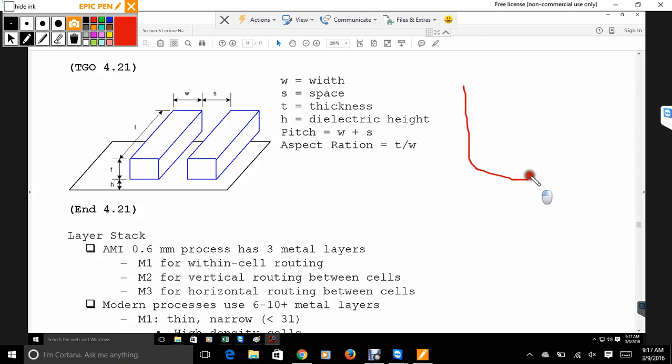And so what's going to happen is you're going to see metal 1 here, you see metal 2 here, and that way this one could go this way, and I'll draw an X indicating it's going into the screen. So you can actually have them running in different directions. So you have to worry about how far these two are away from each other, what direction they're going. You have to know about the width and the thickness of the wire.